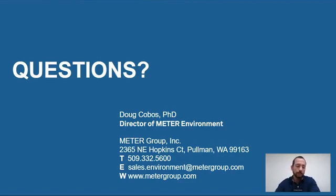And, you know, as Brad was mentioning, there is some power in having both measures, right? So water potential tells you about the availability of the water, tells you where it's going to flow, tells you all these things, but it doesn't by itself tell you about the water balance. And so if you have the water content information and the water potential information, then you really have everything you need to characterize the water in the soil. So there is some power there.